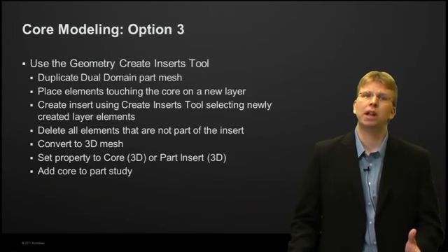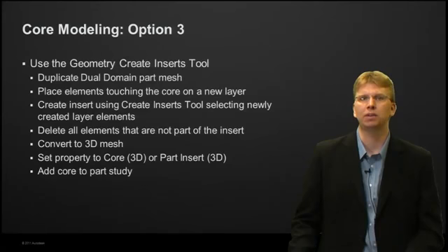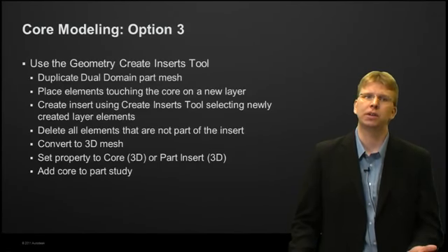Then we're going to delete all the elements that are not part of any of the other insert, clean up the mesh, and then convert that solid insert that we created into 3D mesh. Finally, we'll set the properties of the core insert itself, either core or part insert, and then we'll add that back to the part study.